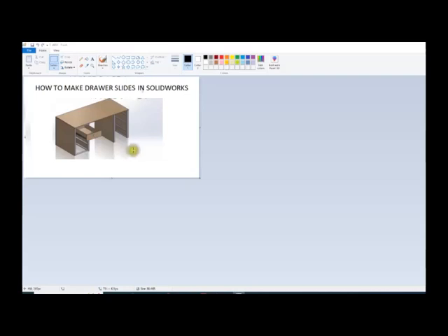files and your libraries. For example, this 1x1 galvanized steel, I thought that was there, and I found out it wasn't. So you have to make this profile in order to use it, like for a simple desk. And how you prepare a new profile for Weldment, this video is about that. It's very straightforward, and we're gonna do it right now.